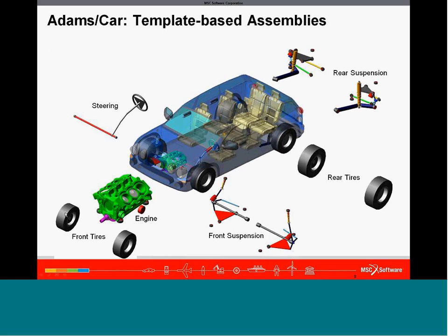So as I was saying, you have different components, and think of each of these components as an individual Adams View model. Not built in Adams View, but built in the Adams Car environment, but having the same concepts. Parts connected through forces, in this case a spring, using joints, and then you have things like steering wheel motion using a driver to apply steering motion, etc.